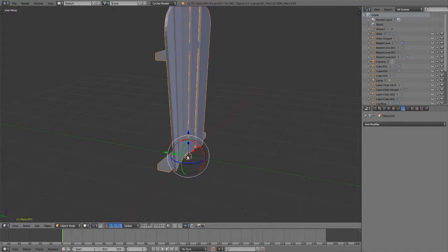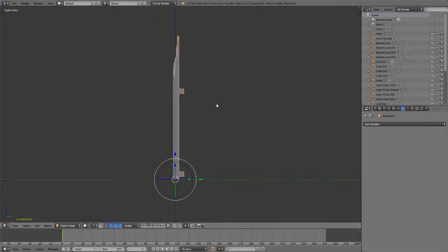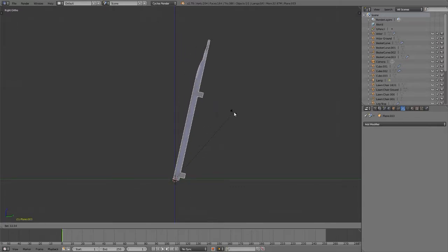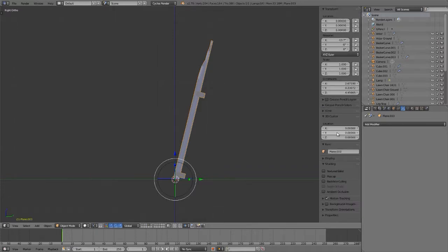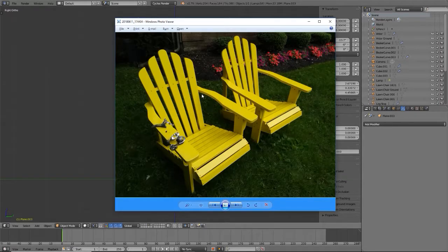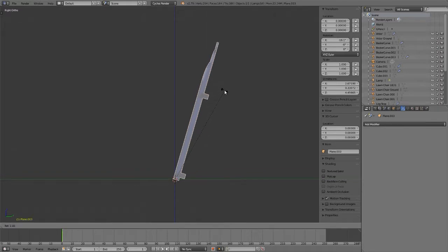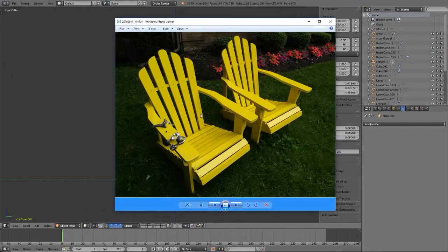Lean it back, go to 5 on the number pad, and go to 3 and lean it back. That's an R. We can lean it back in object mode, and what that will do is preserve the rotation as the object's rotation. Now, technically we shouldn't be doing this to model correctly, but this way, if we ever need to come back, now we know that aesthetically 13.7 degrees in a negative direction along the X was the way we went. I think maybe I'll do that a little bit more. For this project, it's not really that important.